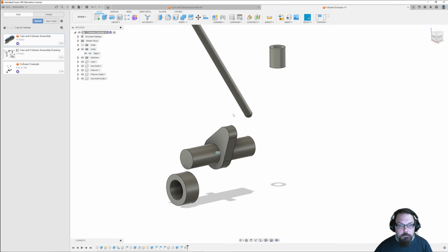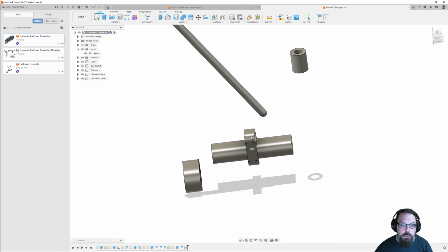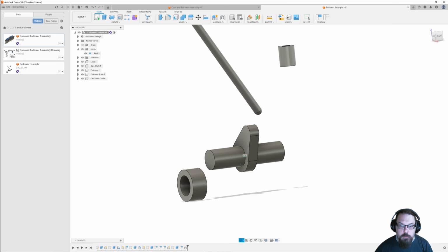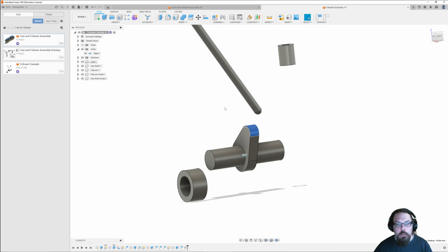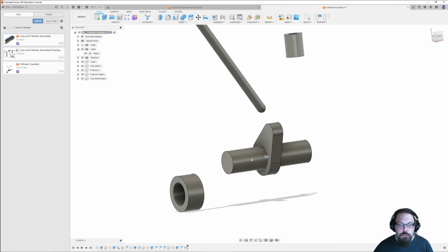And then we're going to click OK. And so this cam lobe should be dead center in front of this shaft right now. The drawings for this week will dictate the spacing for the cam lobes on the main camshaft. In this final assembly, you'll have those spacings called out. So we have a rigid relationship between our camshaft and the cam lobe itself. So they're effectively one piece.